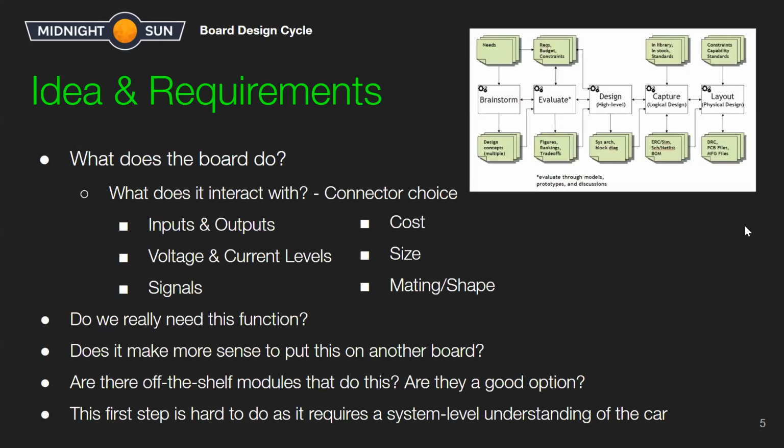Starting with ideas and requirements. What does it interact with? What connectors do you need to interact with those devices? Is it Micro-Fit? Is it a custom connector that stays on our car charger? And what are the inputs and outputs, voltage and current levels that will affect your trace sizing and how you test it? If it's high voltage, then you need different testing equipment for that.